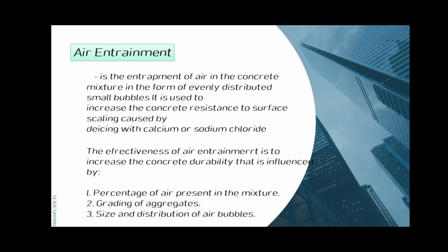Air entrainment is the entrapment of air in the concrete mixture in the form of evenly distributed small bubbles. It is used to increase the concrete's resistance to surface scaling caused by deicing with calcium or sodium chloride.